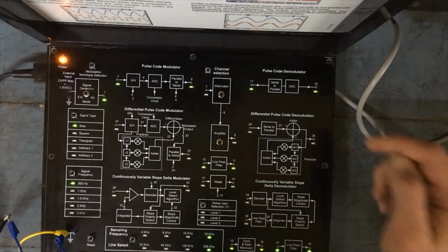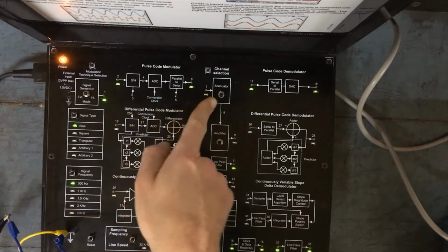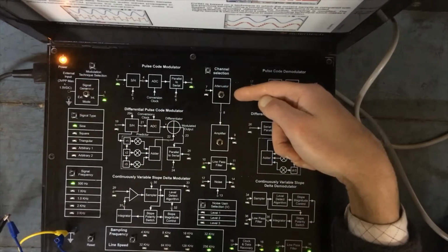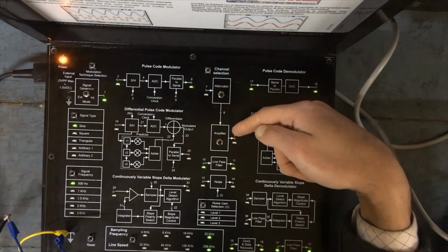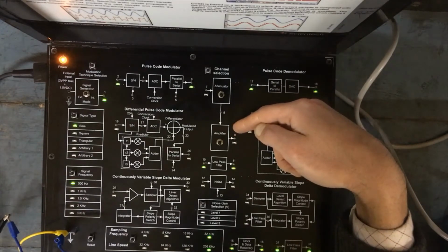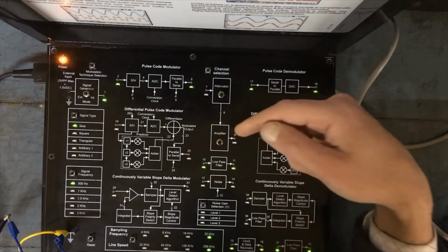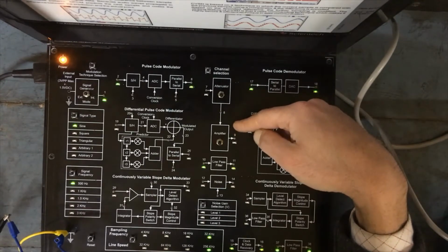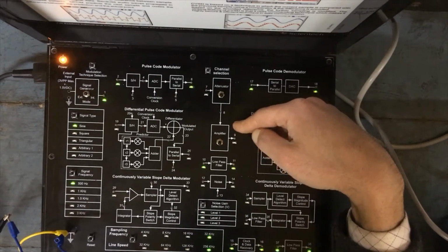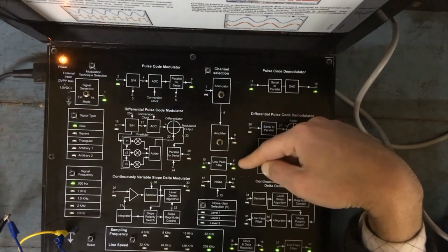Okay, in the receiver section, this was our pulse code modulated wave, which is passed through the appropriate channel model. Either you attenuate the signal, and at the receiver the signal is amplified. This amplification can also, by the way, happen in the midst of the channel at appropriate points, which we call repeaters. For example, undersea optical fibers have regular repeaters every 20 kilometers.